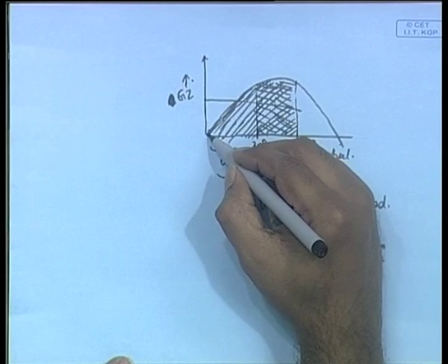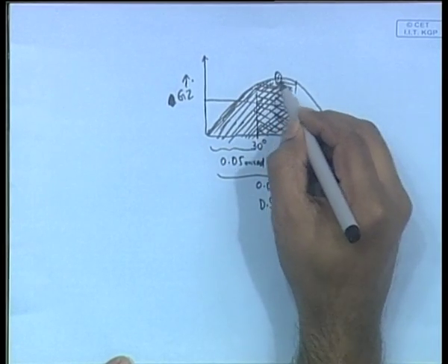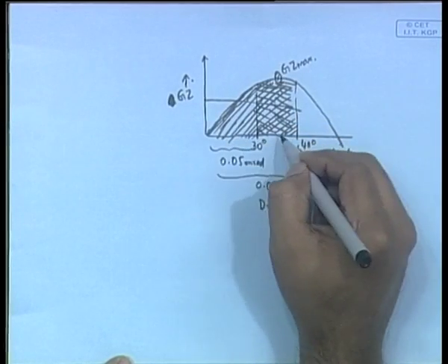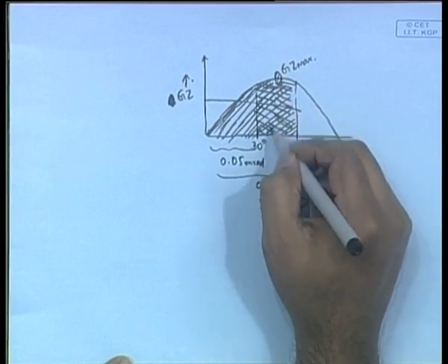It is also recommended that the maximum value of GZ, which is your righting arm, should occur at a value of heel angle which exceeds 30 degrees. So, they do not prefer you to have heel angles less than 30 degrees for the maximum GZ. The position where you get your maximum GZ in your curve, like in this curve, this is where you are getting your maximum GZ. This should always occur at an angle exceeding 30 degrees. So, somewhere here you should have the maximum.